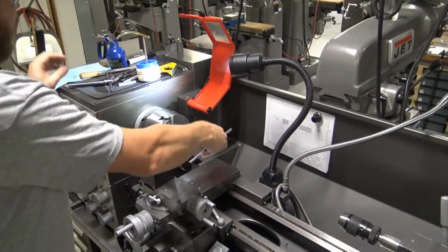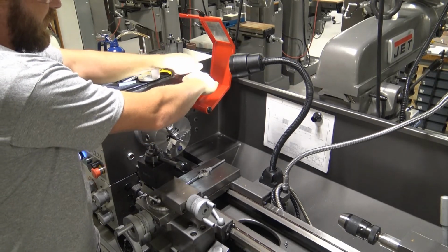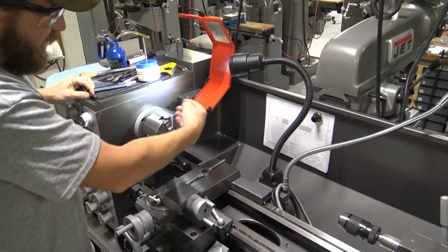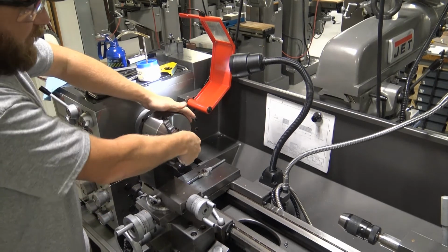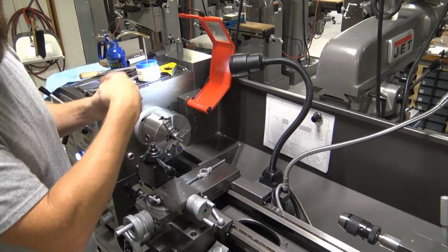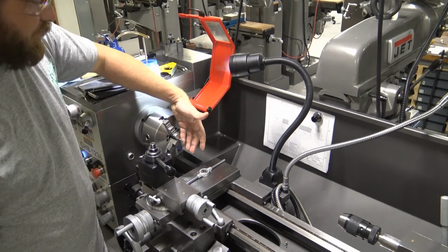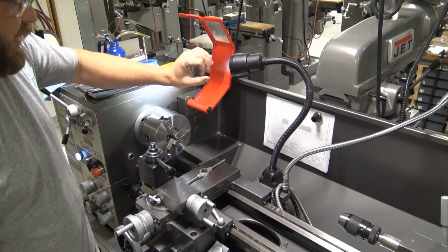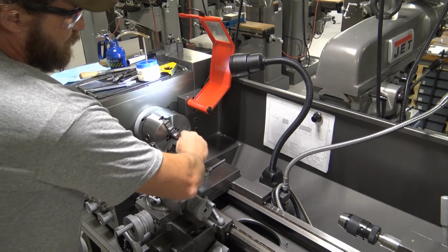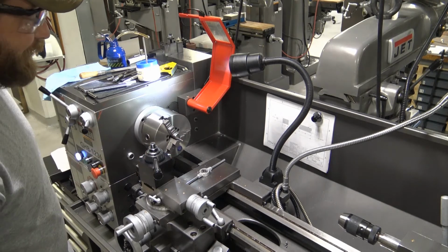Check this, and the last thing is make sure that your workpiece is pretty tight in there. I see a lot of people, when they're cutting these on, don't tighten this down enough, and the chuck may not be spinning, but this little pin is spinning inside the chuck, and then we'll end up scarring and marring the outside. Remember, we use this drill rod for a very specific reason, because it's ground right to a perfect diameter. It's nice and round, so we don't want to mar it up by it spinning inside the chuck. That defeats the purpose of using this material.